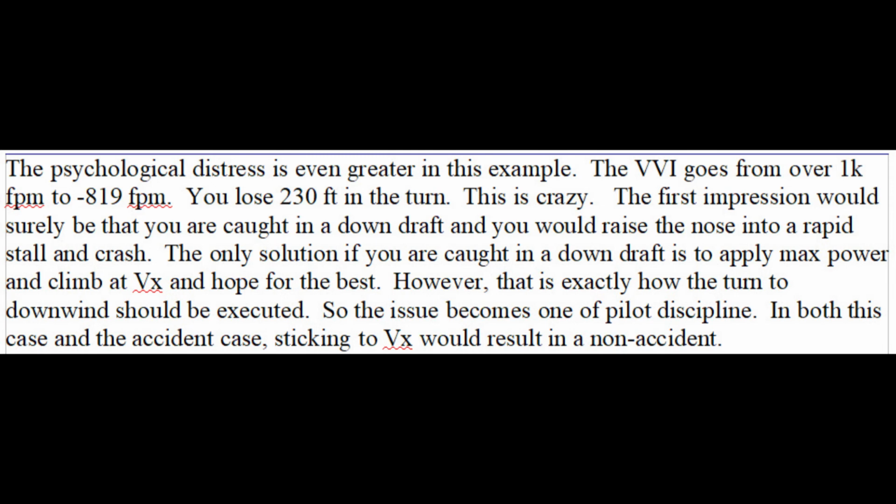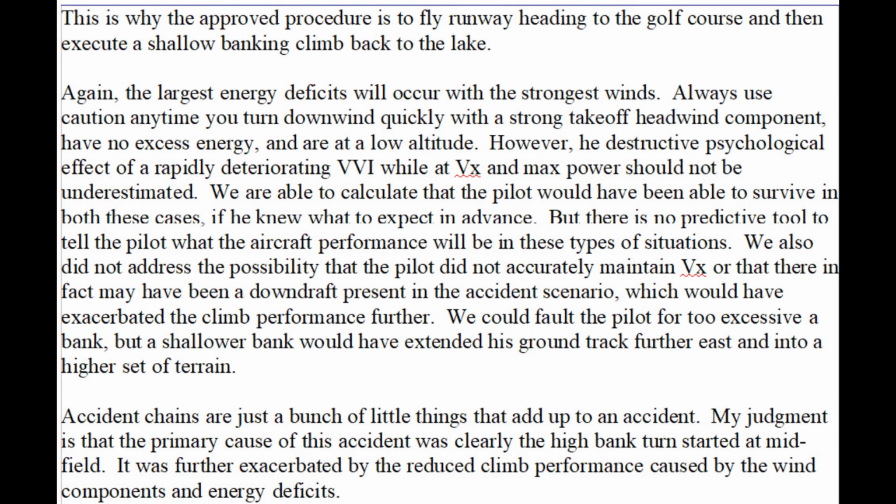However, that is exactly how the turn to downwind should have been executed. So the issue becomes one of pilot discipline. In both this case and the accident case, sticking to Vx will result in a non-accident. This is why the approved procedure at South Lake Tahoe is to fly runway heading to the golf course and then execute a shallow banking climb back to the lake after you've gained sufficient altitude.